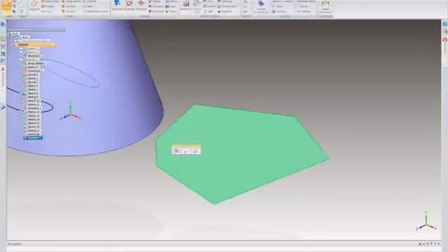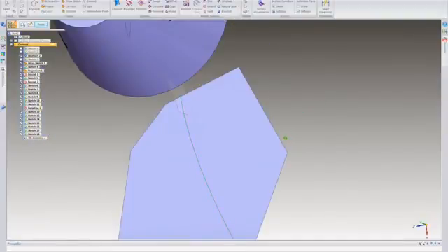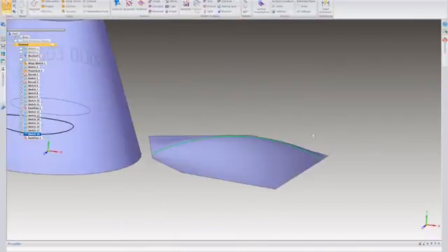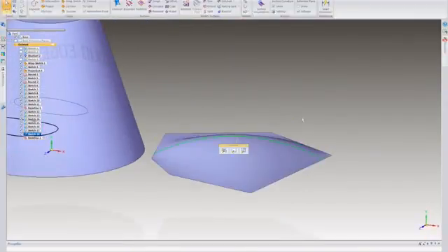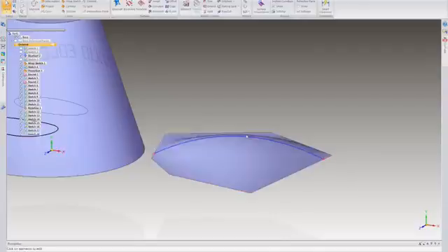Since this is ordered, it creates a sketch before this, so it creates a correct order history. Now I can dynamically edit that surface. And let it catch up. There it goes. So what I did is I just created an open profile. I did a closed bound with the new closed bound. I did a redefined surface. I added some sketch control points. Then I can come over here and modify these control points by just using the dynamic edit.